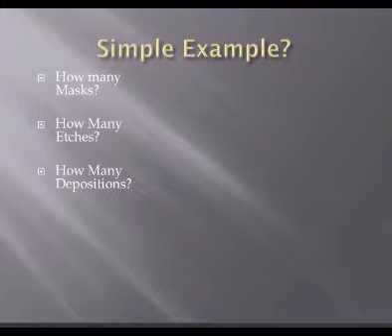Okay, how many depositions? But isn't developing different than etching? Oh, yeah. Developing a pattern is not the same as etching. Yes, you're right. But some people would consider that removing material. So you could count that as a type of etch. But in industry, they don't call it etching. It's developing, right? So we call that develop. We call taking the resist off of the material strip, or resist strip, okay? Or ashing. There's another way we can do it.